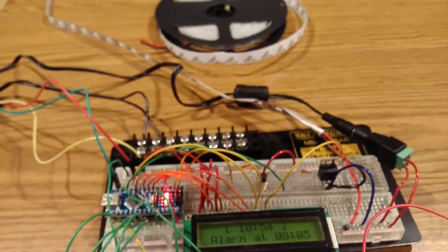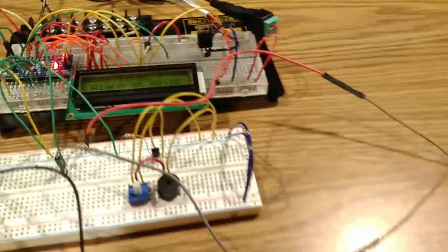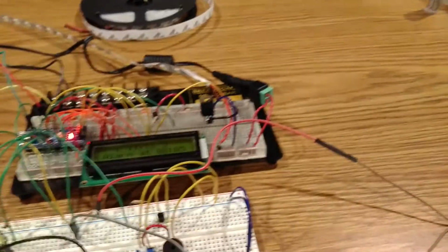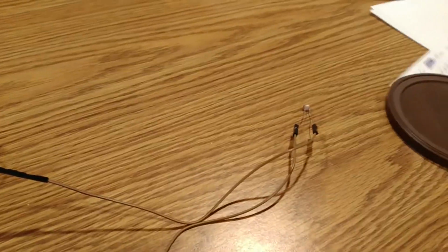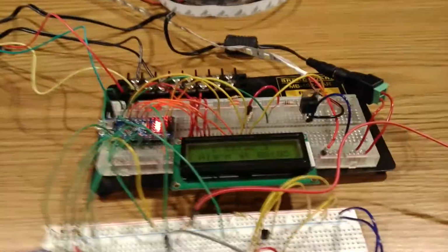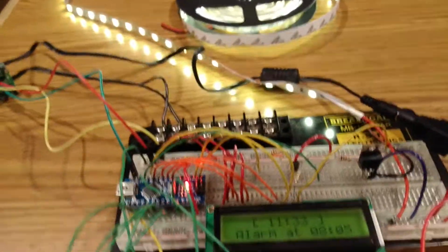The other feature is what I call the auto light or night light, like I mentioned before, and that utilizes both the proximity sensor and this photo sensor. Right now we have plenty of light, as you can see. If I go ahead and cover this photoresistor though, I'll just cover it with this lid here, this should be dark enough to trigger it. This time when I pass my hand by the proximity sensor, the LED strip actually turns on as well.